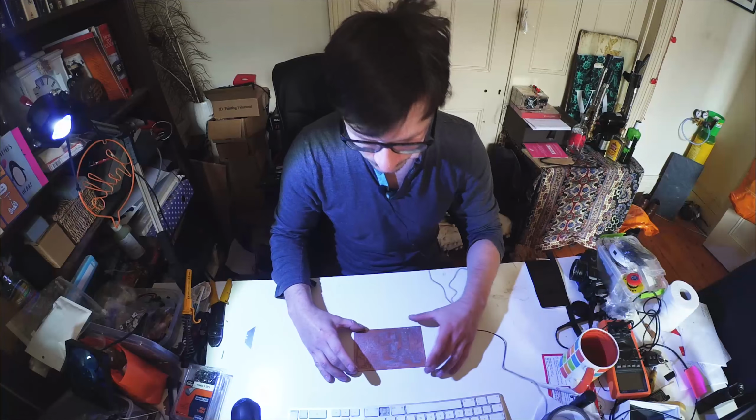I drilled the hole all the way through into my bed at 1.4. I think I had a drill bit that measured slightly under, so that's a nice tight fit. And then I enlarged this hole to about 1.7. Just basically means that the pin goes through this board very easily, with a very, very small amount of play, probably less than 1/10 of a millimeter. And when it goes into the bed, it's actually a friction, an interference fit, so it's not going to move, and it provides pressure holding the board down. So that's the way I did it.